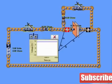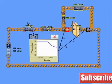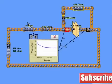If we close the other switch, we'll be able to discharge the capacitor. Same value resistor, no battery, but we're discharging through the 10 ohm resistor. And we see a very typical discharge curve and back down to 0 volts.